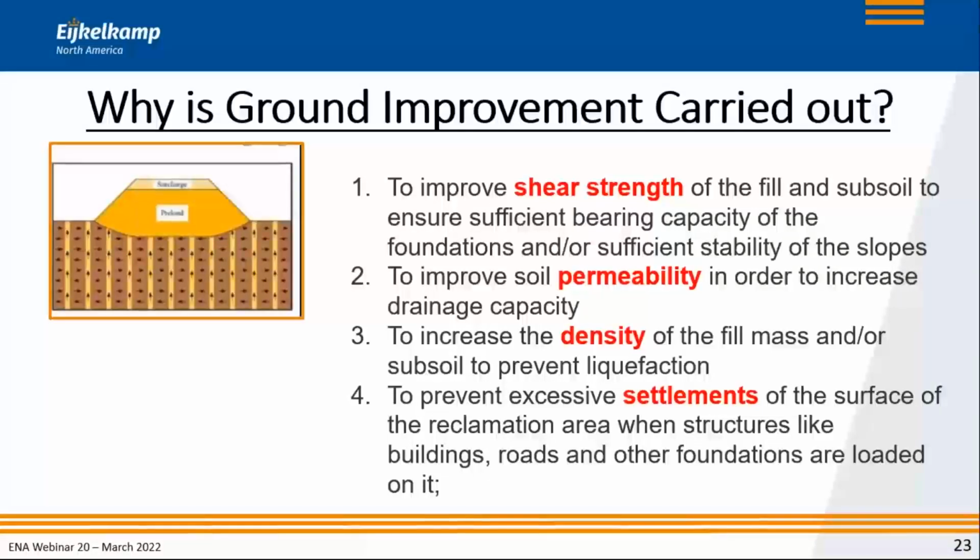So what about permeability? What you see there on the left-hand side is the surcharge with a preloading, and we have applied some vertical drains. But the main thing is that we have to figure out what this horizontal movement of the water towards the vertical drains is, because that will determine the effectiveness of what you're achieving.